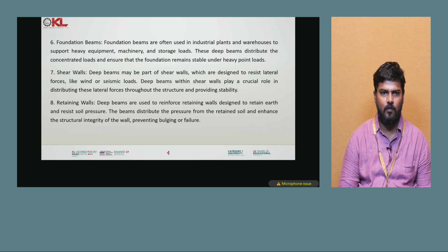And coming to the next one, the foundation beams. Foundation beams are often used in industrial plants and warehouses to support heavy equipment, machinery and storage loads. These deep beams distribute the concentrated loads and ensure that the foundation remains stable under heavy point loads. Shear walls: deep beams may be part of shear walls which are designed to resist lateral forces like wind or seismic forces. Deep beams within shear walls play a crucial role in distributing these lateral forces throughout the structure and providing stability to the structures.